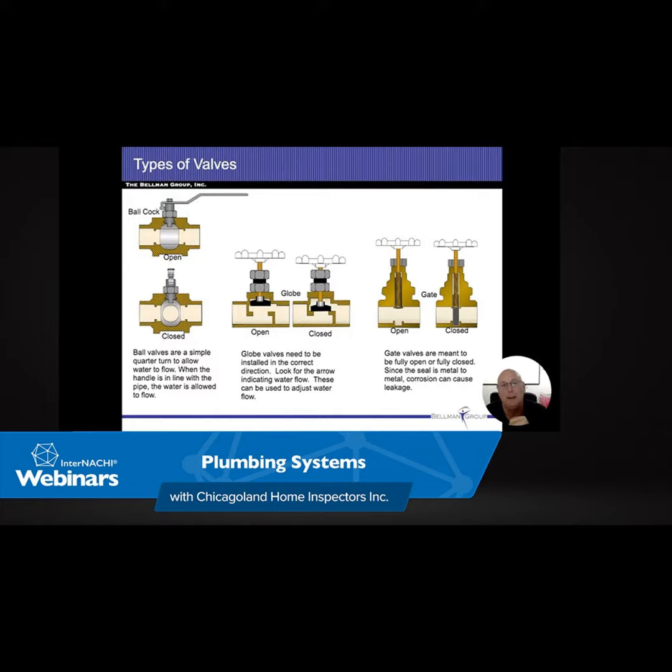Empty out all your supply lines. Open up all the valves so everything can escape. And then you go ahead and close all the valves. Turn your service line back on again. And what we do is now we added that air back into those air chambers, and we'll have that cushion come back for us. The mechanical ones, if those failed, the only solution that I'm aware of is replacement. I don't know if there's any repair to those.